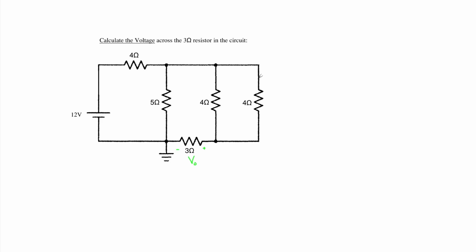So let's go ahead and simplify this to an equivalent resistance. Well, 4 ohms in parallel with 4 ohms is half the original value of both resistors. So, omitting this whole branch and writing an equivalent resistance of 2 ohms, we have simplified this circuit enough to be able to start writing some of our equations.